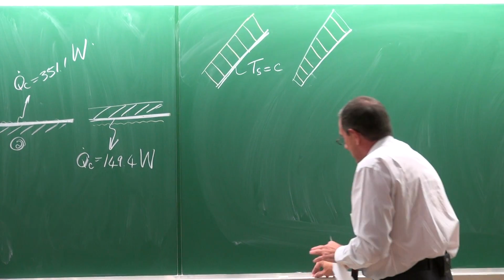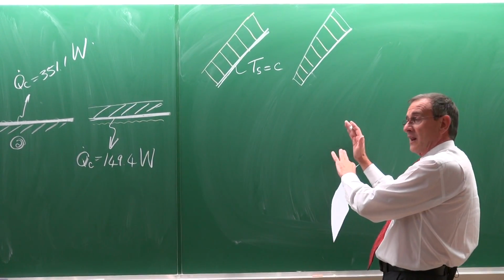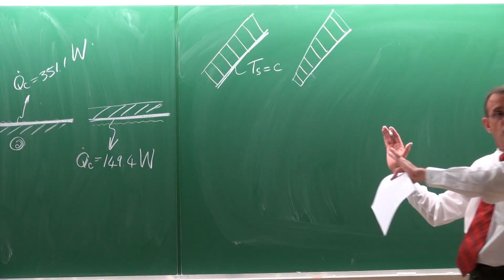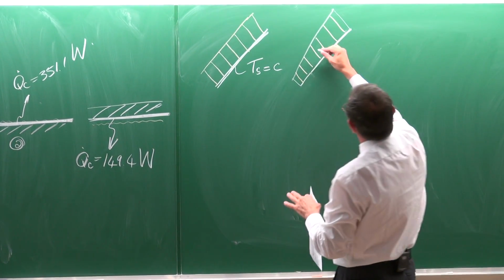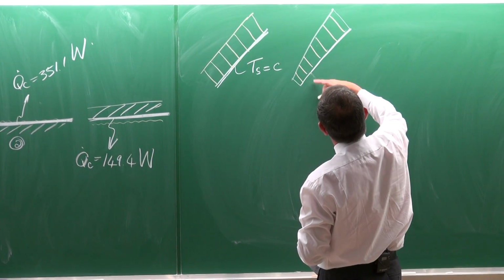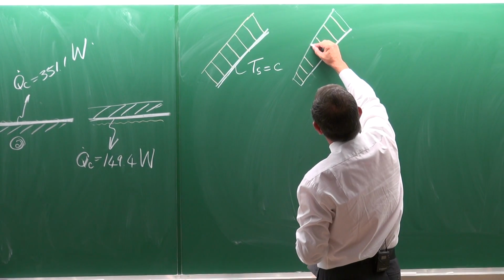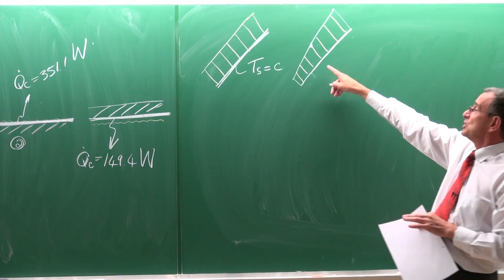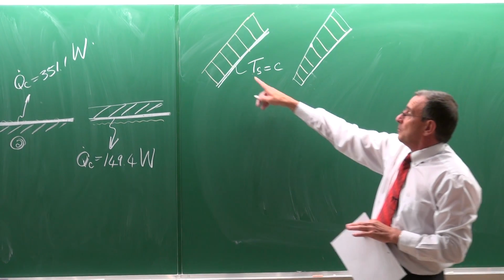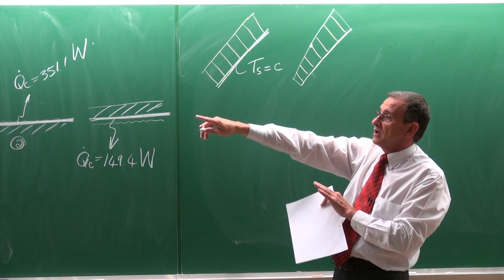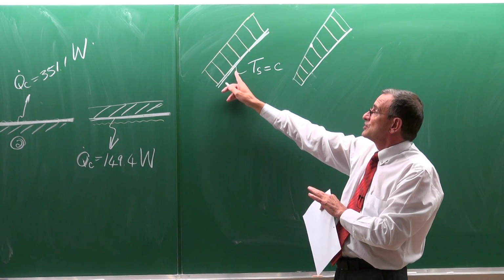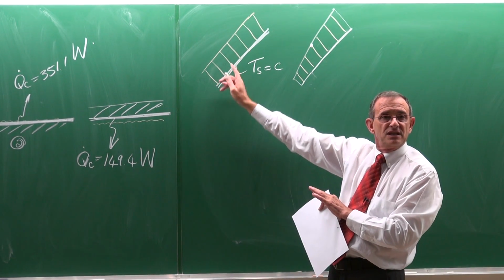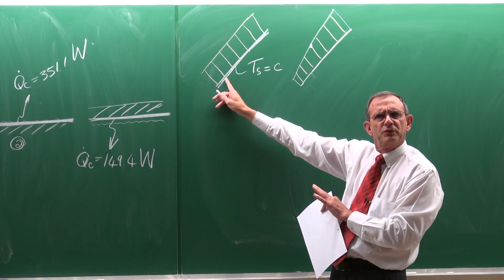Now, the fine print again will direct you in terms of the equations to be used. For example, with a constant heat flux case, you need to use that temperature Ts, which is the average temperature halfway through the plate. But if you start with a problem like this, normally the surface temperature and the environment temperature are given, so you can calculate the film temperature.